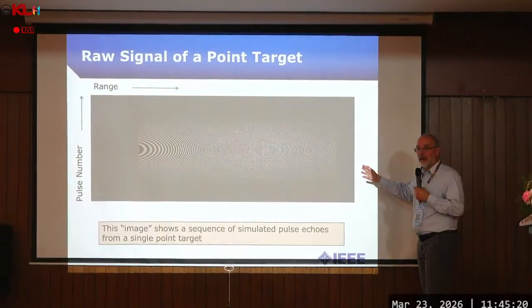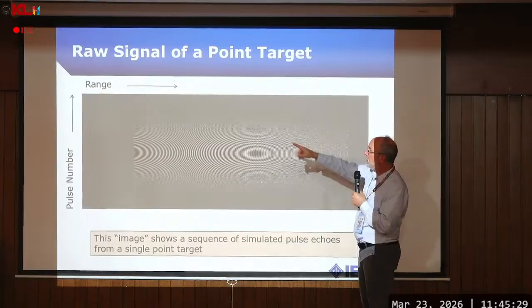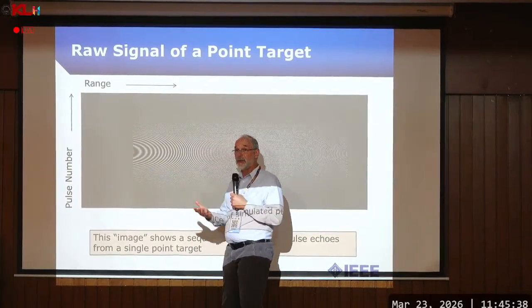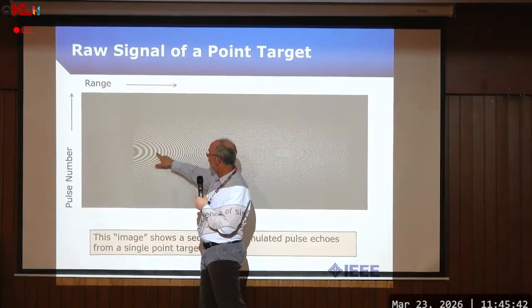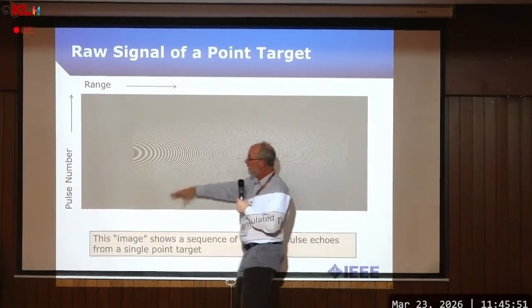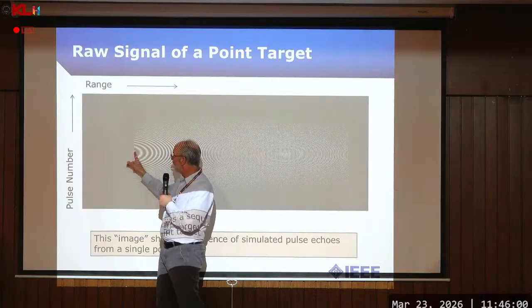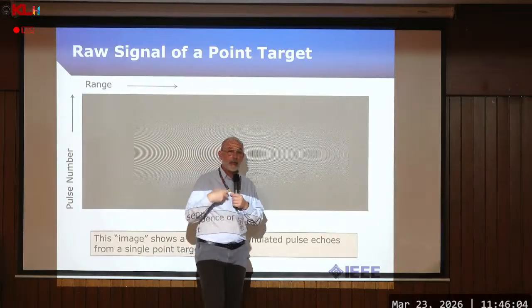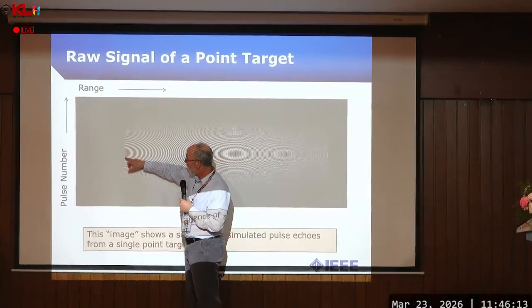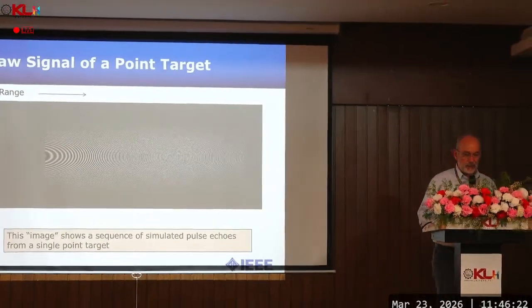So if you were to look at a very idealized image of raw acquired data from a radar, where we're flying along this direction and the range direction is going across, and we had a point target that is located right here, then that chirp signal that we're transmitting has this quadratic phase or linear frequency characteristic. But as you move away in time from where this position is, the distance is slightly different. The distance from here to here is different from the distance from here to here. So you get a different phase value that's associated with each of those chirps. So you can see there's also another chirp in this other dimension. So we get a chirp in this dimension, and we get a chirp in this dimension. We should be able to exploit that for getting high resolution imagery.